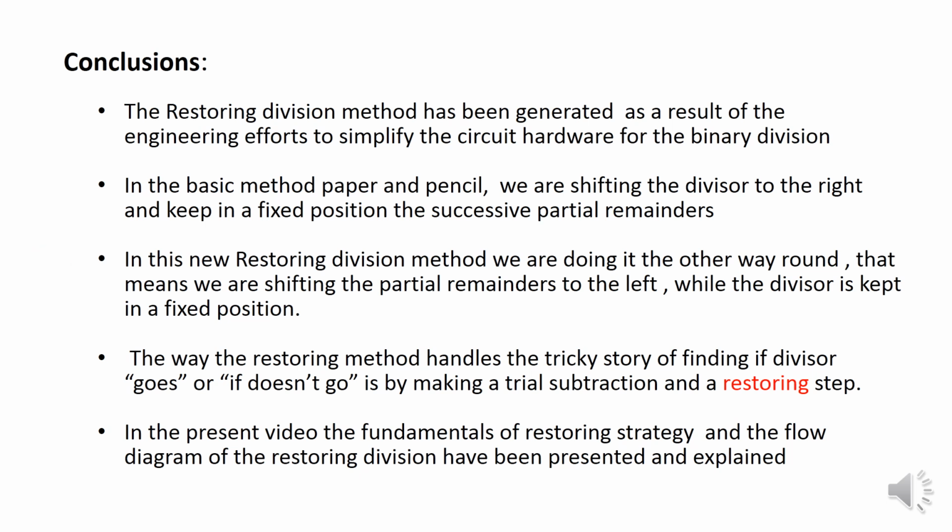But in this new restoring division method, we are doing it the other way round. That means we are shifting the partial remainders to the left while the divisor is kept aligned in a fixed position. The way the restoring method handles the tricky story of finding out if the divisor goes or if it doesn't go is by making a trial subtraction and a restoring step.